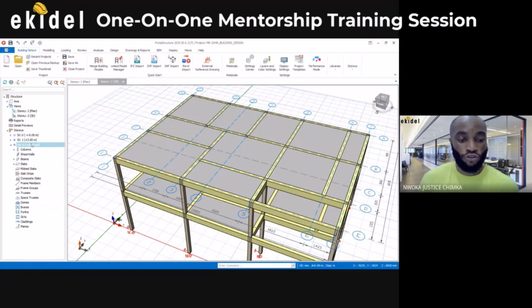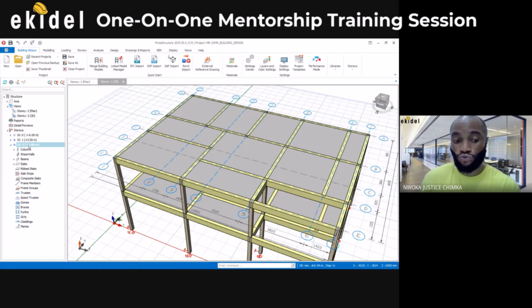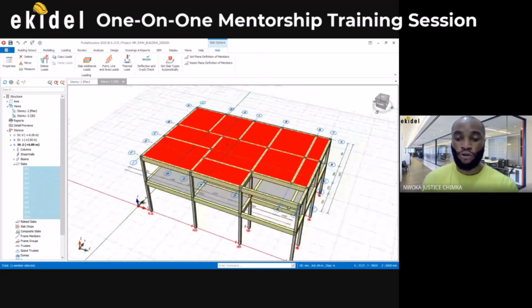Once you're on that story, on your story 2, can you hear me? Yes. So once you're on your story 2, come to slabs here and drop down this slab. You see all the list of slabs on that story. Click on the first one, hold your control key, hold your shift key, and then click on the last one. It will pick all the slabs on that floor.